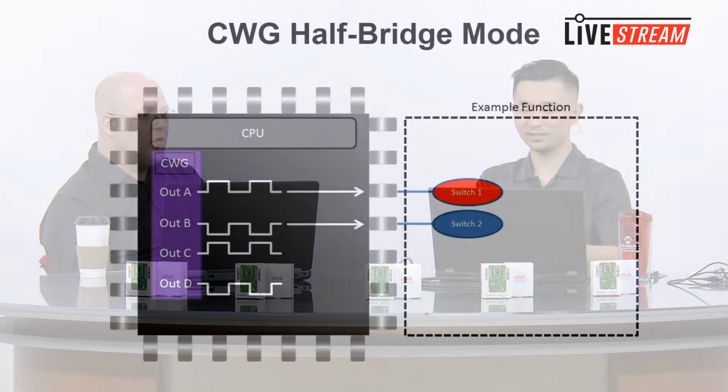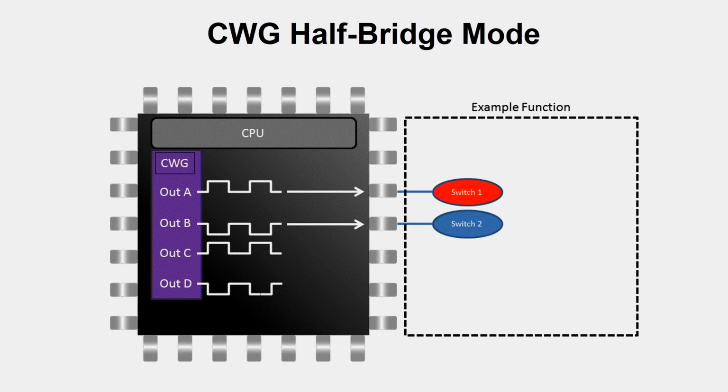And on the top, you probably have P channel, and on the bottom end of the H bridge, you probably have N channel MOSFETs. Yes. But that's a very common configuration for driving a DC motor bidirectionally. Yes. Or if you want to do a stepper motor, that kind of thing. Right. Okay, cool. And also it has the half bridge mode, which is doing the actual complementary output.